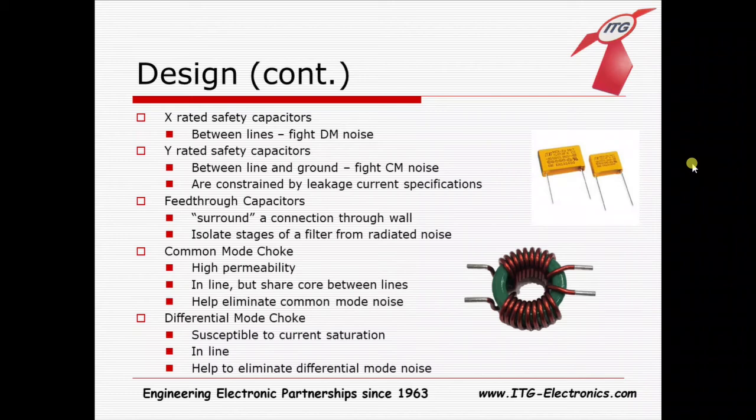A common mode choke, this is a type of inductor. It's a very special type of inductor actually because of the way it's designed. You can kind of ignore saturation current or the possibility of saturating the core, which is this little green material here. It's a magnetic core that you wrap the windings around because these windings are in opposite directions and they, from design, balance each other out from a current standpoint, and the core actually sees no current passing through it.